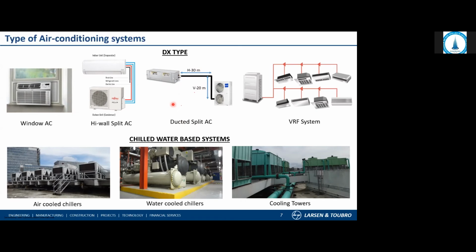If you have a large requirement in a particular building, let's say a 10-story building, whether residential or commercial, your indoor unit requirement would be more. In that case, you have a wonderful opportunity to propose the VRF system, that is, variable refrigerant flow. It has two basic benefits. One is that it works as a centralized plant. You can put the outdoor units at the terrace, run refrigerant pipes to each floor and zone, and as per your requirement, propose various types of indoor units available for VRF. So that is one thing you can use as a centralized part of it.